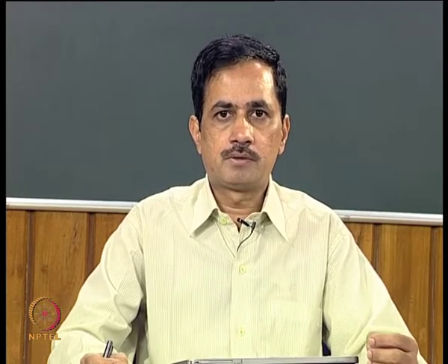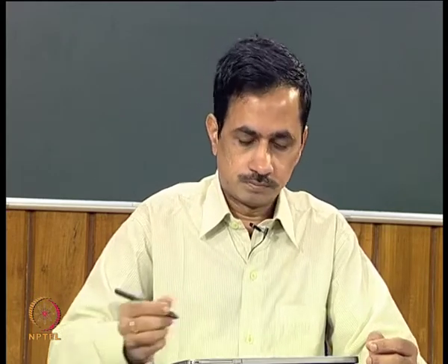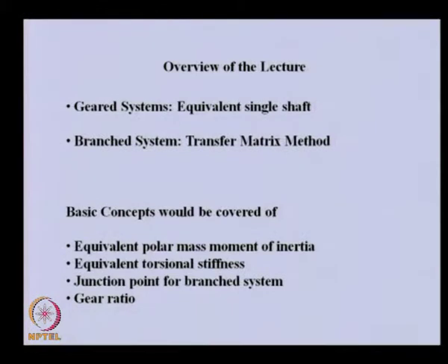and the extension of that as a branch system, in which from one particular point multiple shafts are connected through gears. So, let us see what things we will be covering. For geared system, basically we will try to convert the geared system to an equivalent single shaft system, so that whatever previous analysis we did, we can apply to this particular system.